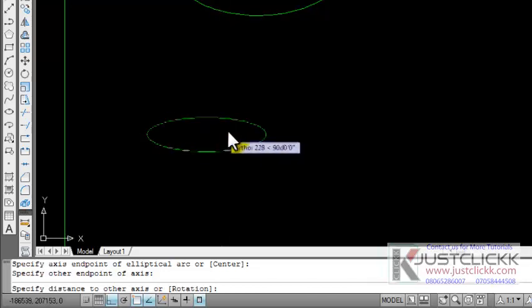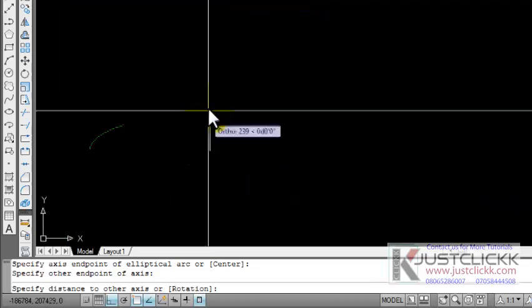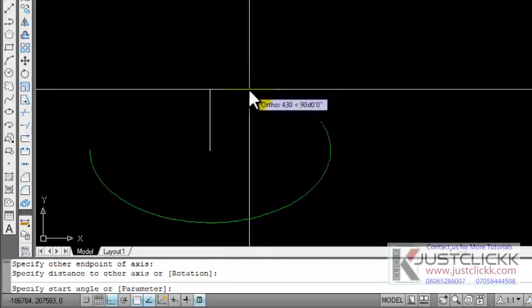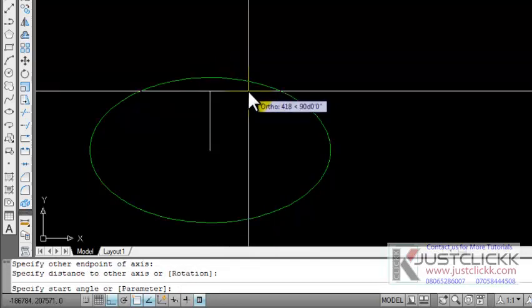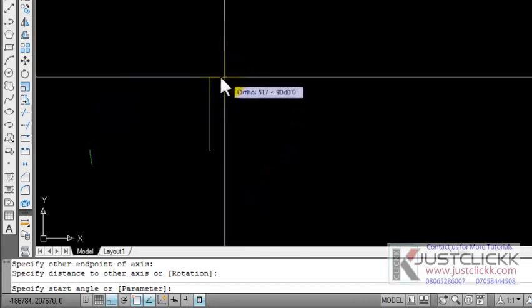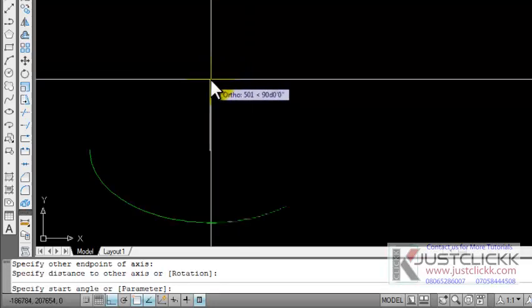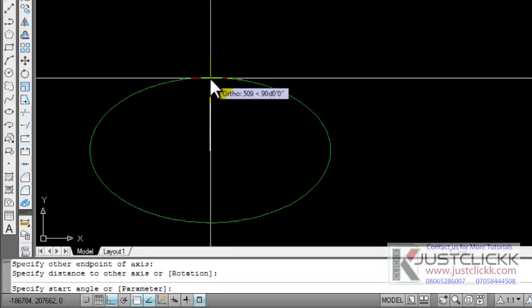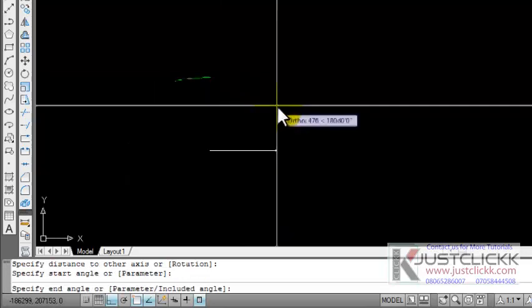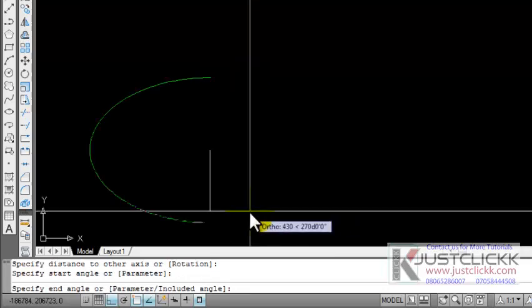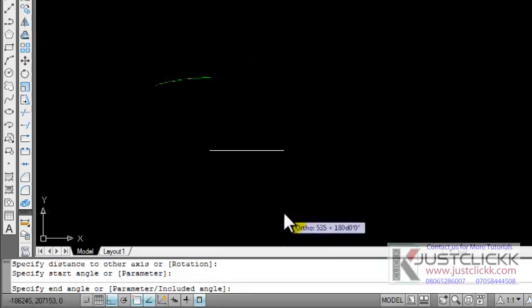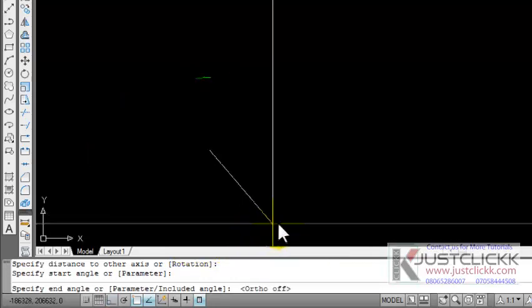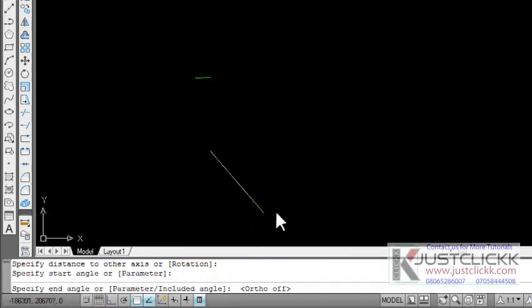I'm doing it conceptual. I'll just get the shape I want, and then I'll click and specify the start angle to be cutting off, because this is an arc. So I will specify somewhere here at this edge, and then I will go this way down to somewhere around here. Okay, let me disable my auto snap by pressing the F8 key, so that my movement will be diagonal.